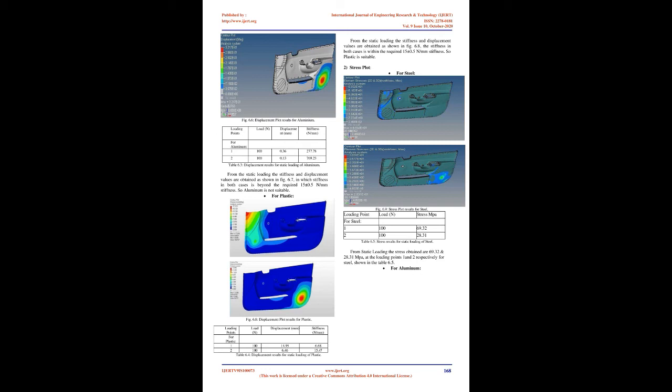In this step, the constraints, geometry, loads and mechanical properties are applied to develop matrix equations for all elements, which are combined to generate a global matrix equation of the structure. The form of the individual equations, as well as the structural equation, is always F equals Ku, where F equals external force matrix, K equals global stiffness matrix, U equals displacement matrix.